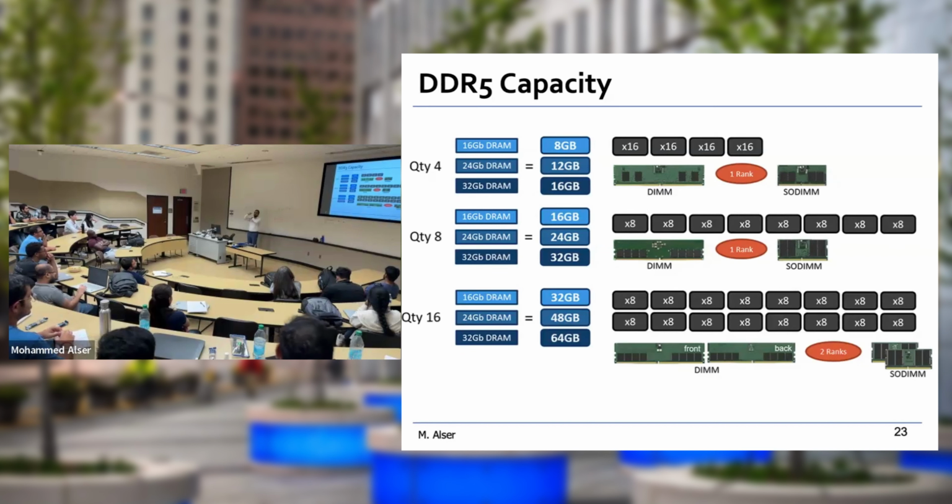So you access the first rank, you get something from it. Now this rank tries to pre-charge or tries to do any housekeeping. Then you can access the second rank as you are doing housekeeping in the first rank. In this way, yes, you may increase the throughput, but not doubling it. Okay, you may overlap some cost and reduce the overhead. Hopefully this is clear.